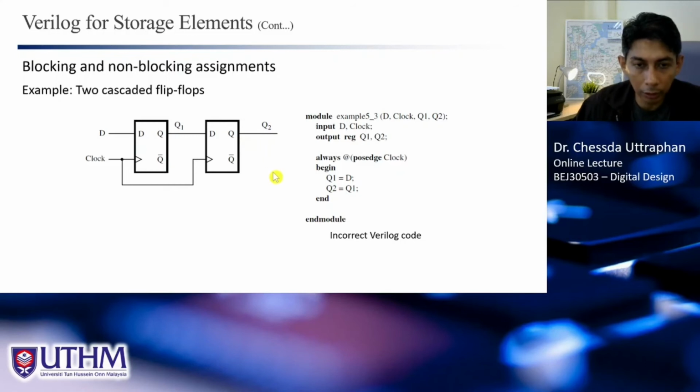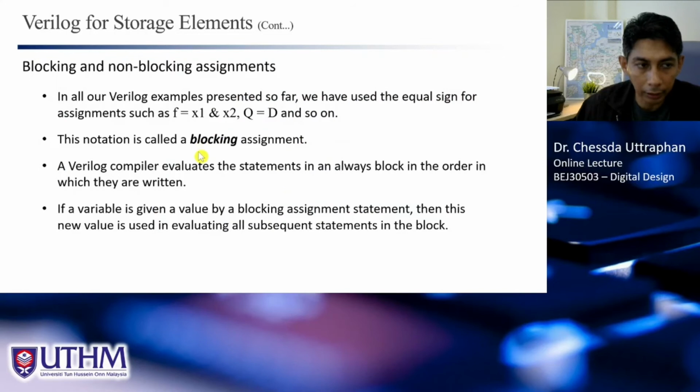But by using blocking assignment, the Verilog compiler will evaluate the statements in an always block in the order in which they are written.